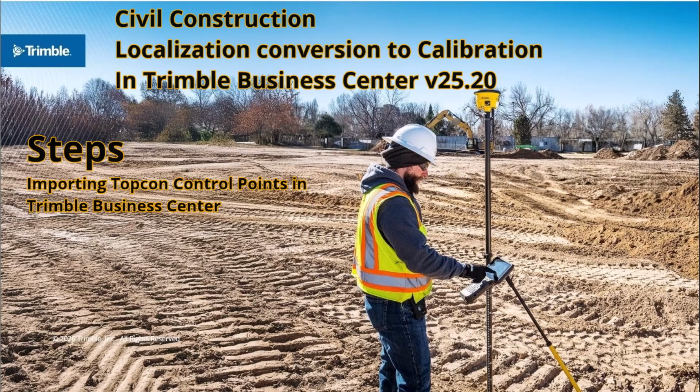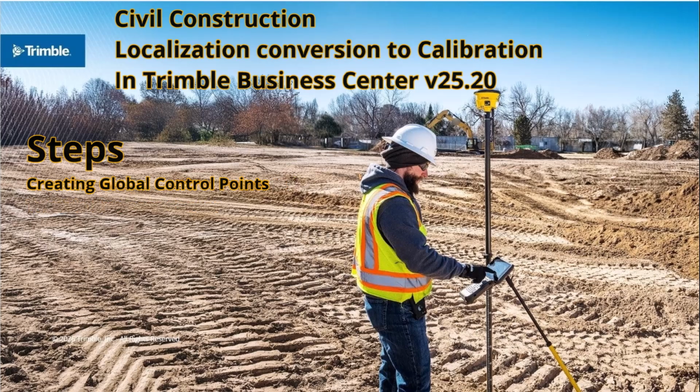We'll cover the following steps: exporting your Topcon control points, importing your Topcon local control points file into TBC, creating global control points from the Topcon control point information, creating a site calibration in Trimble Business Center using the local and the global control points, reviewing your control and GNSS points, along with creating and saving a site calibration file in Trimble Business Center for future use.